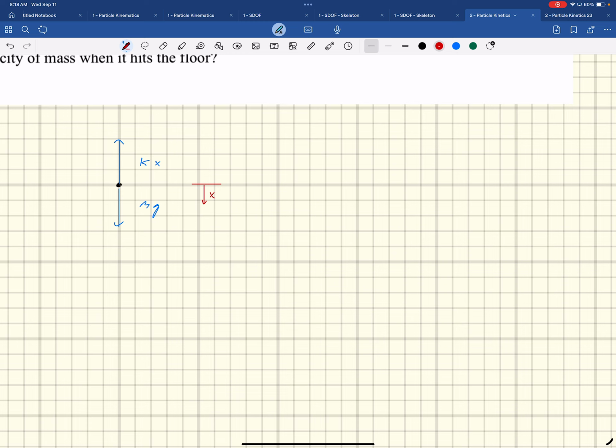And so if you're trying to figure out which direction the spring force goes, you think of if the object is moved in the positive x direction, which way does the spring act? In that case, it would go up. I'd pull it down, the spring would apply the force up. If I had defined x as being positive up, then I would move the object up, and my spring would go down. And then the signs work out if you do it that way. That's one of those little steps I mentioned earlier. There's a reason why I drew it up, and that's a rule that I stuck to. The rule is, if I move it in the positive direction, which way does the spring act? Then you draw it in that direction.